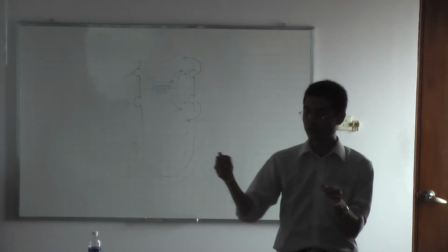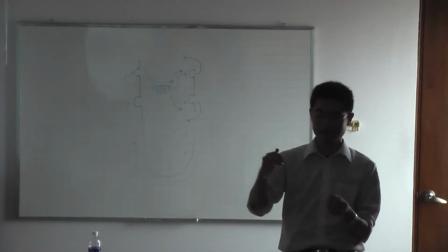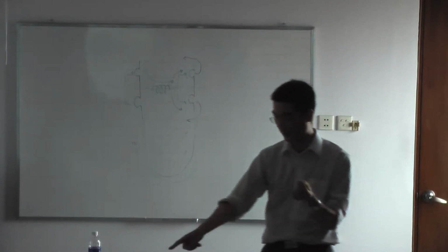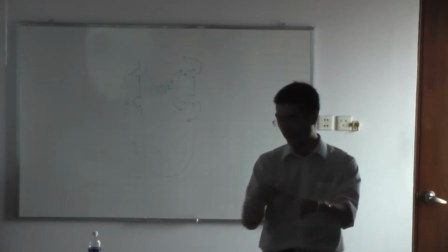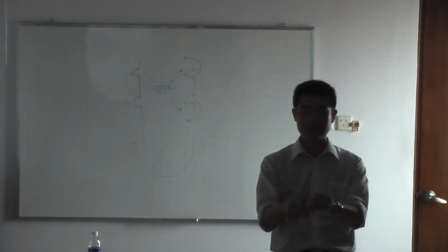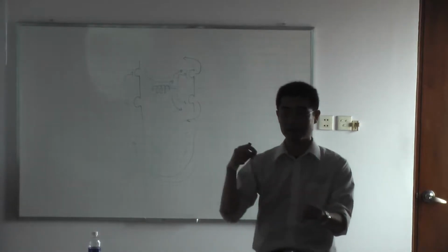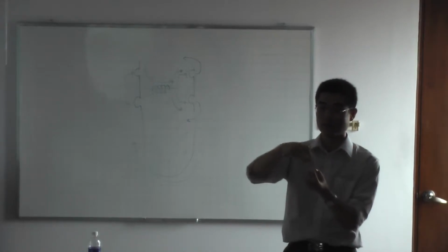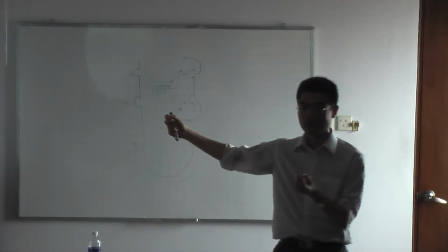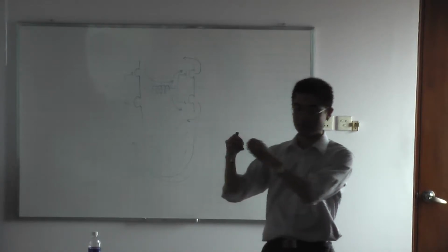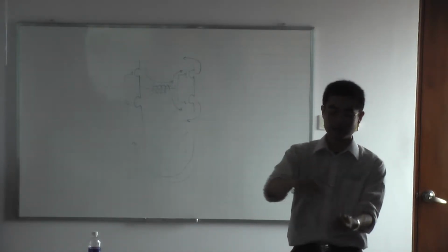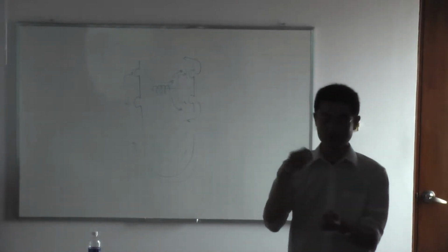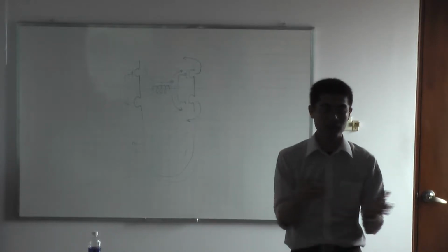So the prober has a 50 ohm system impedance up to the tip of the pins. At the top of the needle, there is a connector, and these lines are designed with 50 ohm system impedance. And these are SMA connectors, so SMA cables are attached to the connectors and connect to, for example, the oscilloscope. So from the oscilloscope input terminal to the top of the needle, we can have a 50 ohm line, so that it is not disturbed by the connections.